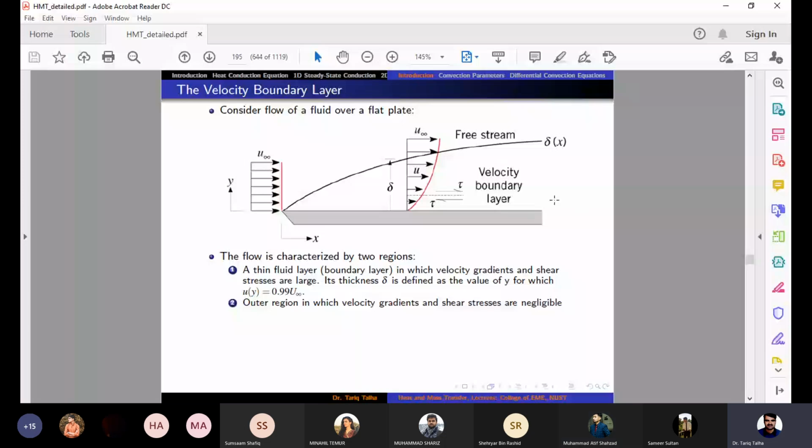Yes sir. So that's why this thing grows in y, because now more molecules would have less velocity, because as we move along x, the drag force would continue to act. So that's why the velocity in a streamline would decrease in the boundary layer, and that's why the boundary layer would grow in x.